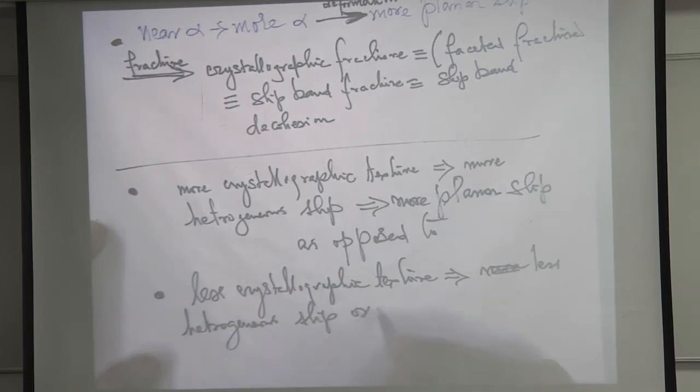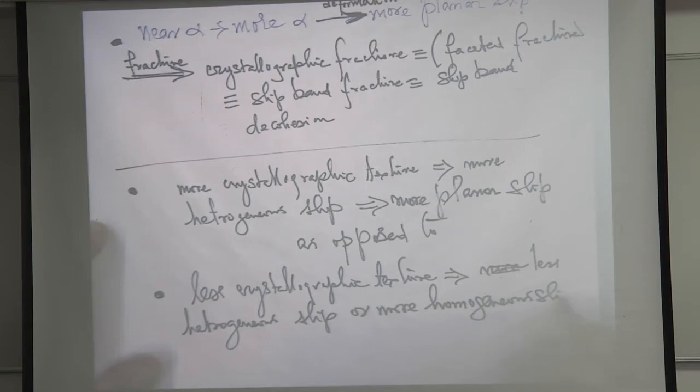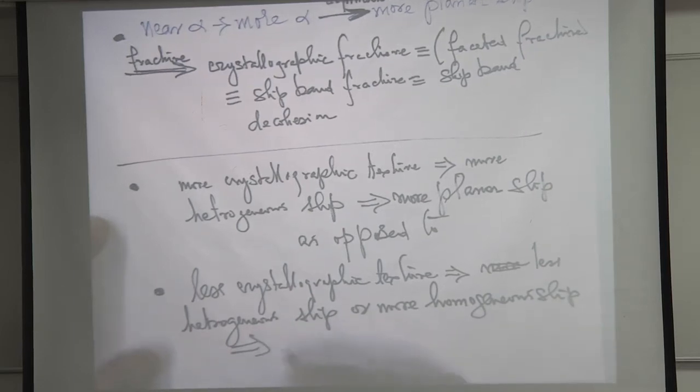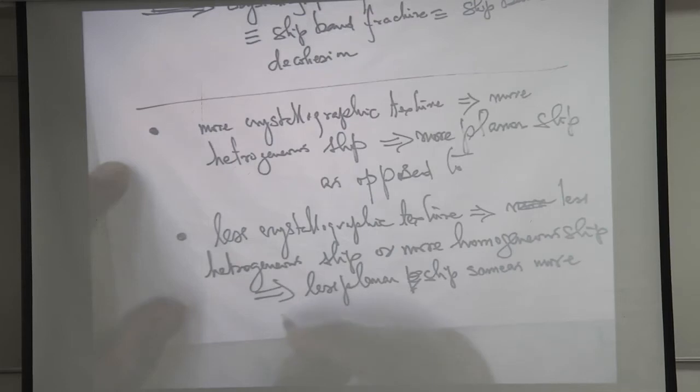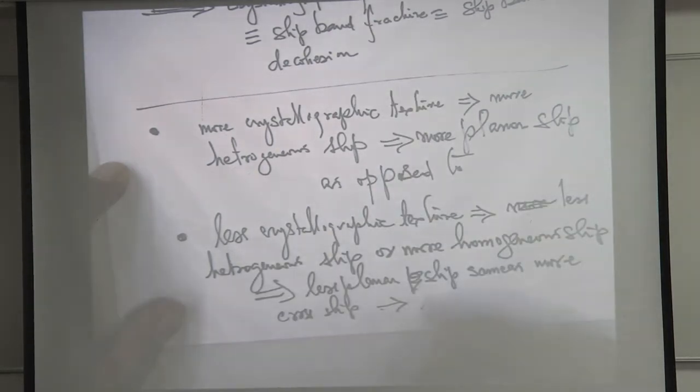Less planar slip, same as more cross slip, and the fracture would be less slip band decohesion, less crystallographic fracture.